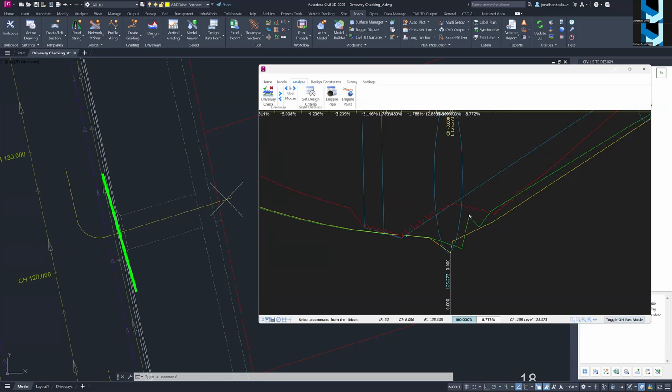I guess this is one of the issues with using a tool like this, and particularly for those of you that are doing this by hand, this probably wouldn't come up as a clash. The reason is that it's about the pen thickness of clashing, but also because the wheel, as outlined in the Australian standard, is essentially like a pin. And in reality, a wheel is not going to be positioned directly inside the invert. It's more likely to be overrunning. So in this scenario, I would be hesitant to say that there is a clash just due to this very, very small amount that we're actually clashing here visually in this window.